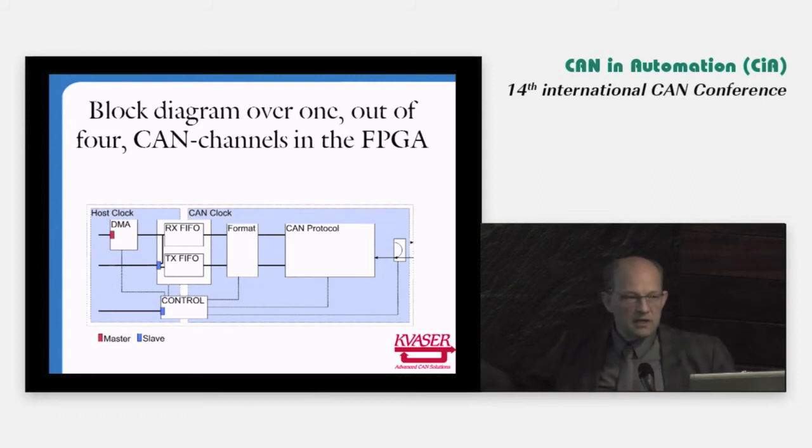So we don't have much use for filtration and things like that. Everything we get here jumps into the RX FIFO, the same as the tagging information in the core. We have only one stream and just put it up to the PC application, and they have to take care of the information. Normally there's only 1 or 2 messages in the FIFO, because it's DMA, so it goes to PCI Express immediately up to the application.